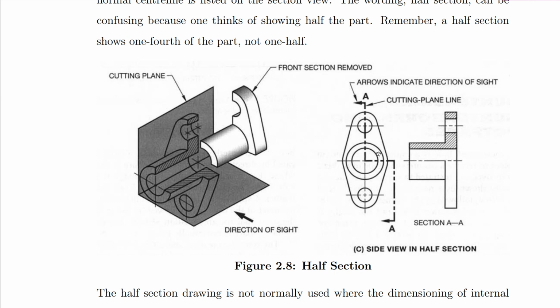Here you'll see that this hole that we have inside here, a portion of it is revealed, and we are going to have this as a continuous line. This hole we have revealed, so we have continuous thick lines here. Then you realize that all the other features are gone, they are no more there. We don't see them here, not because they are not there, but because we are now interested in the sectioned area of the object. So where we have revealed, that is this continuous line.